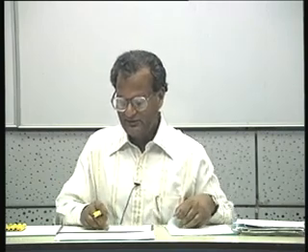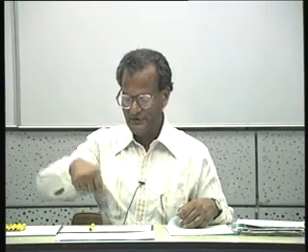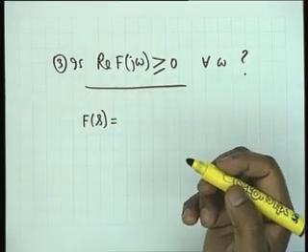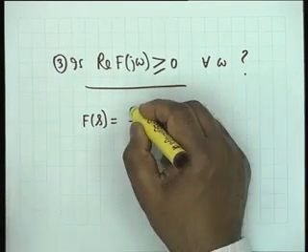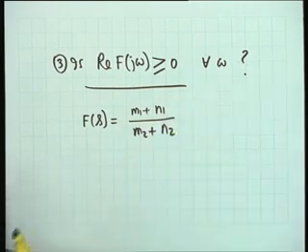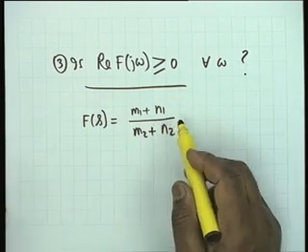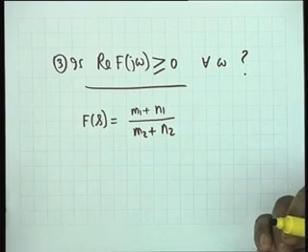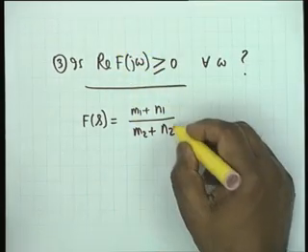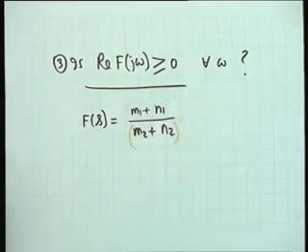This testing, although it contains an infinite number of points from minus infinity to plus infinity on the j omega axis, the testing is in fact very simple, because if you recall we had done this, that if f of s is written as m1 plus n1 divided by m2 plus n2, where small m stands for the even part and small n stands for the odd part, alright, then you recall that by multiplying the numerator and the denominator,